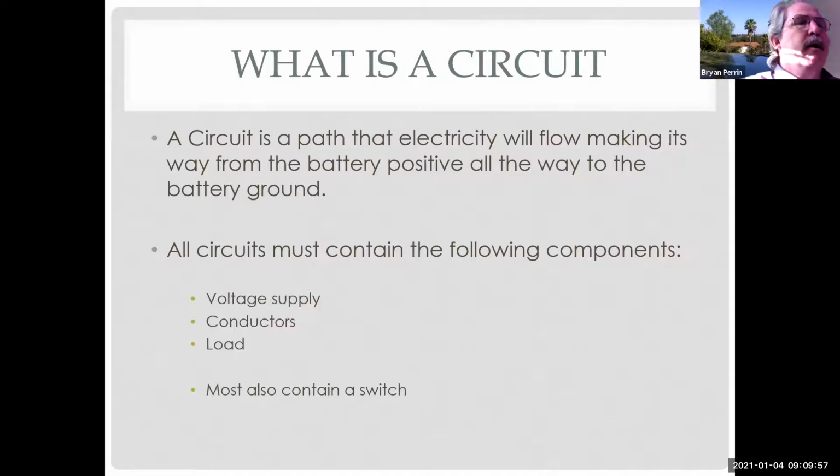Also, when we get into wiring schematics and we look at wiring on vehicles, we find that we use wires for the power wires, and we use very few wires for the ground wires by comparison. So it makes sense to start at the battery, trace my circuit to my load, and then find its way to ground and back to the battery. It just makes a lot more sense trying to fix cars.